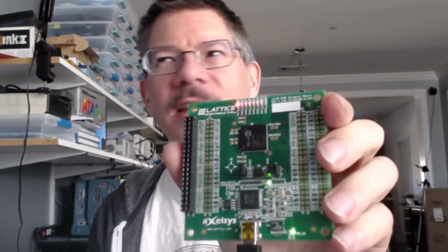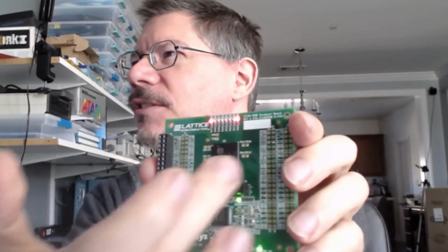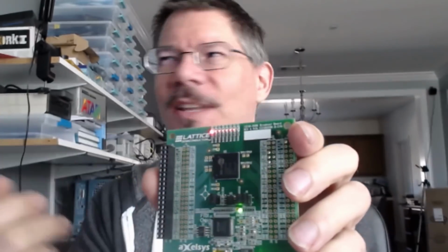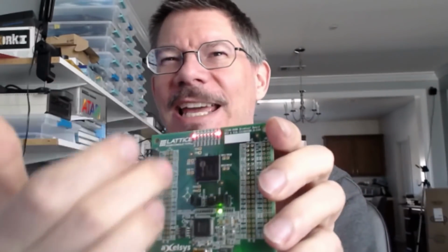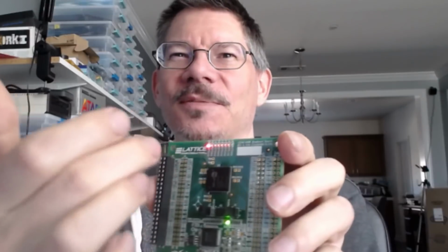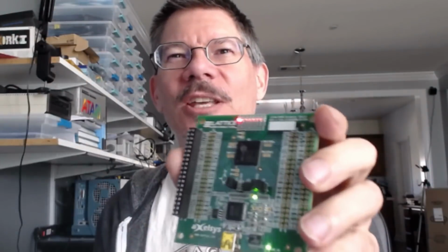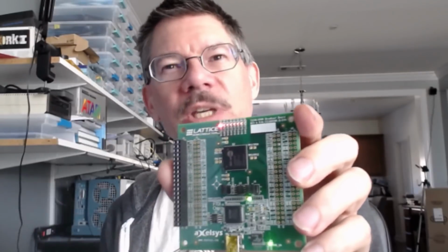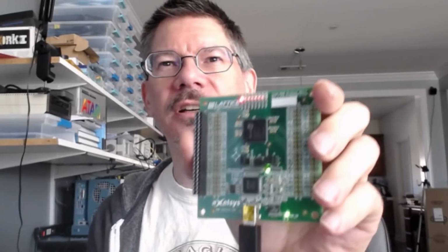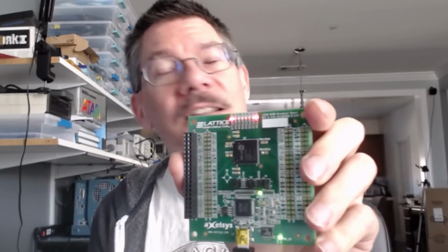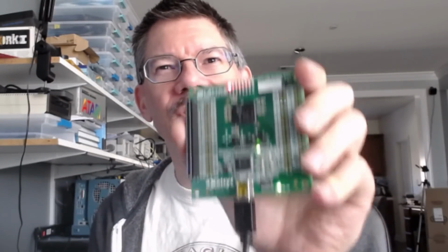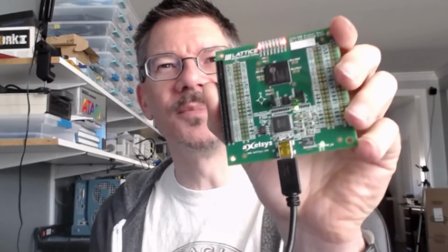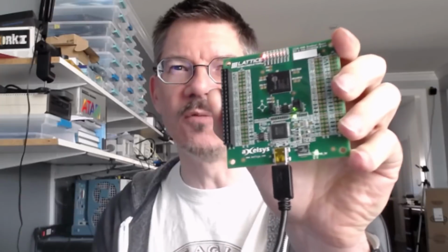Now the interesting thing is that there's this other LED which is lit, like up here. Sorry, I'm looking at the video and I'm trying to move my hands in the right direction, but everything is upside down and backwards. But anyway, you can see that one of the LEDs is also strongly lit on. Again, we did not specify what the output of that LED should be, so effectively it's random. So if you have outputs, make sure that you set them to some known value, otherwise they'll just be random.